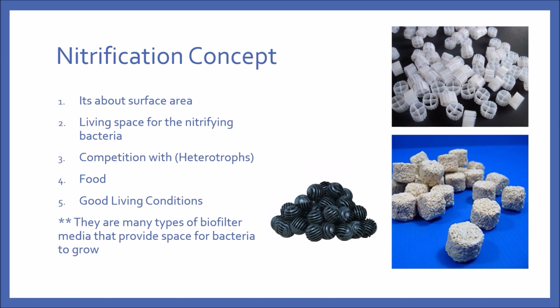What we have here in these three pictures are all what we call biological media. They can simply be made up of plastics. This is what we call the traditional bio balls, this is what we call K1 media, and this is what we call ceramic media. Essentially, they provide plenty of surface area for the bacteria to reside on and repopulate, as well as consuming ammonia into NO2 and NO3.